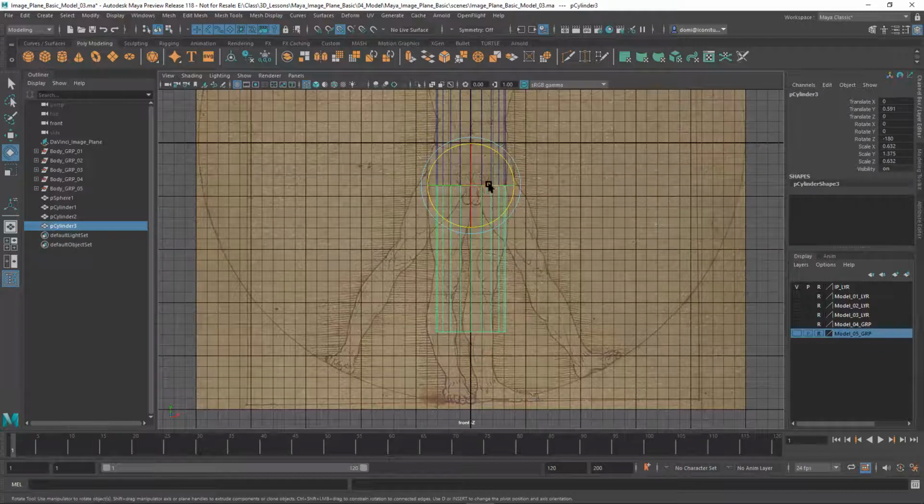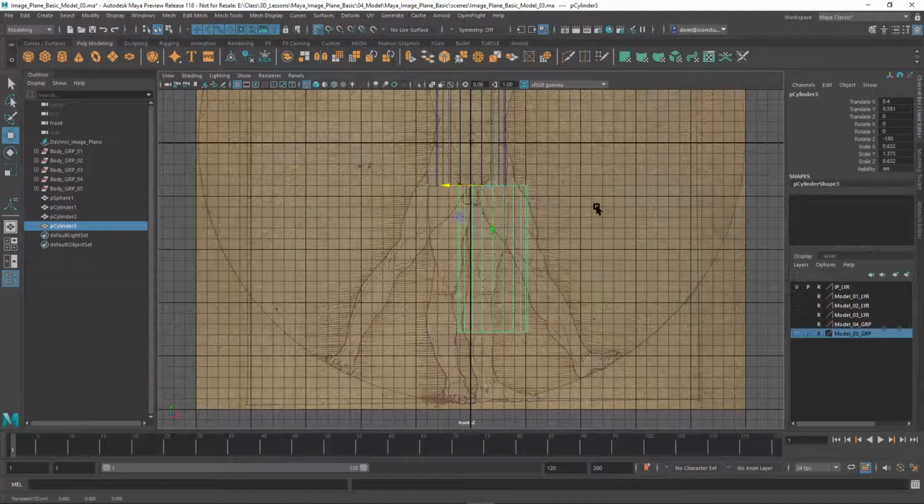So I have the grids, as I said before, that's why I made the grids a little smaller. So they kind of match a little bit. If I was actually modeling this precision, I would probably even make the grids smaller. But then it gets a little hard to see. All right, so what I'm going to do is move this over. So I'm going to move it over to a grid point right there. Okay, so I'm going to go hit on my move key or my move icon. And I'm going to switch back. I don't want to be snapping to points. I want to be snapping to grids. Okay, so I'm going to move that over. There we go.